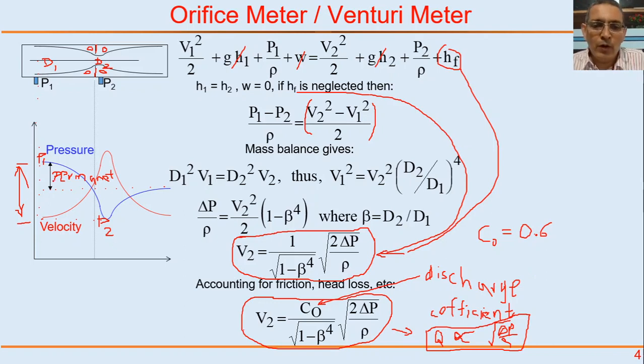So these rotating vortices are what cause the pressure drop, and this is what causes the permanent pressure drop. Therefore, using an orifice causes a permanent loss in the pipeline. If I had not used it, P1 and P2 would be nearly equal. P2 will still be less, but only very slightly less, because it's only this much amount of straight pipe.